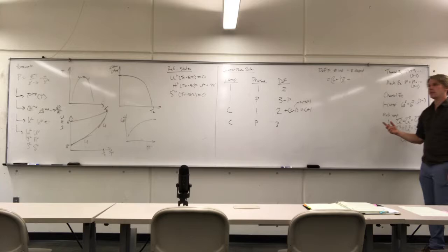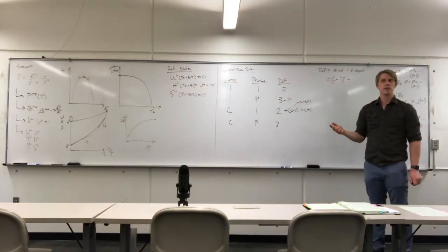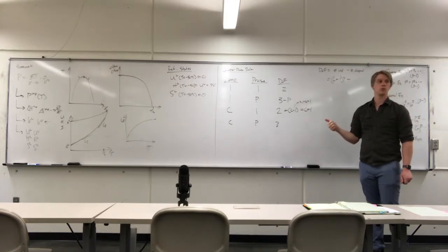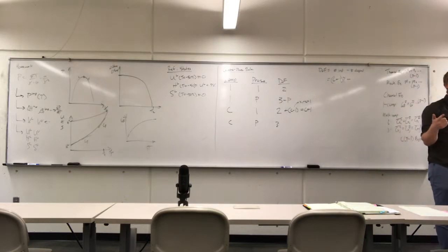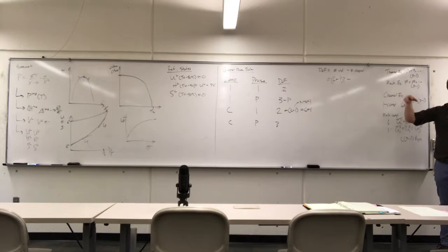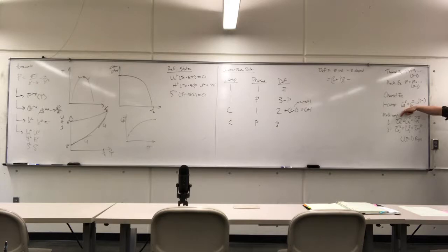So we could think of a scenario that's not uncommon in, let's say, an oil field scenario. You could have an aqueous phase, right, because oil is almost always produced with water. You can have a vapor phase, right, where the light ends of the crude oil, the natural gases, boil away, and you can have a liquid phase. Which means that for every single component in, let's say, crude oil, which could be millions of components, which you need to break down into pseudo-components, otherwise the math becomes intractable, we have to make sure that the partial Gibbs is constant for every component across oil phase, aqueous phase, vapor phase. All of them have to be in equilibrium together.